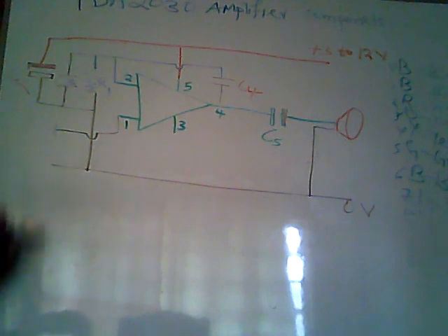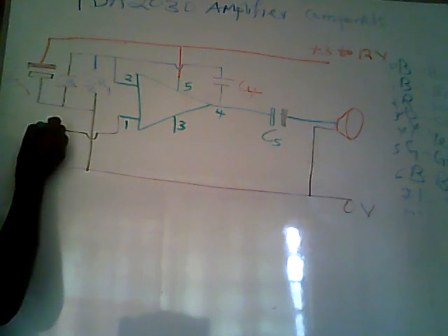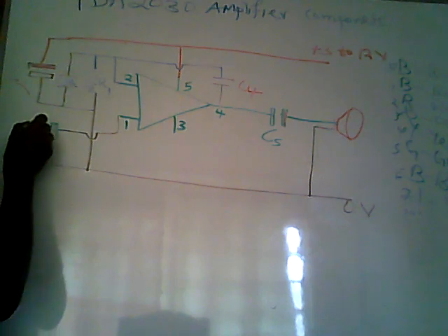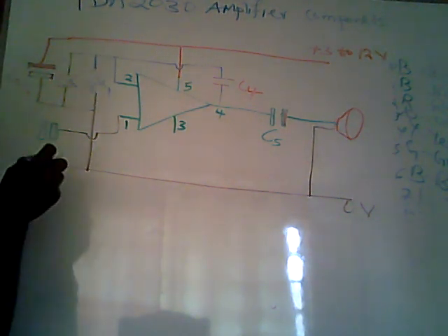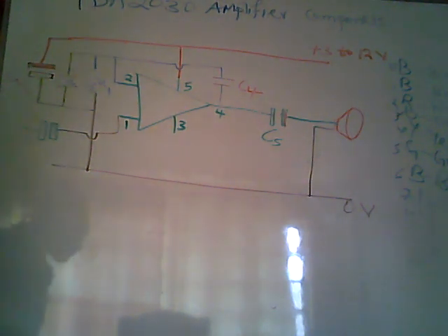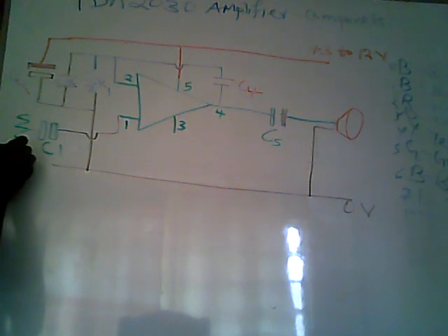So you can see there, that is the pin, and it has a capacitor there. We talked about this capacitor, capacitor number 1, that filters the signal before it enters inside the transistor. This capacitor is going to the variable resistor.